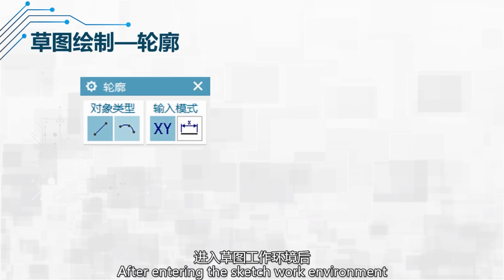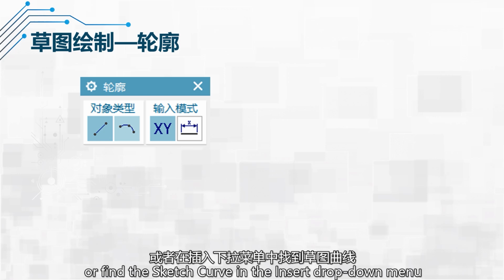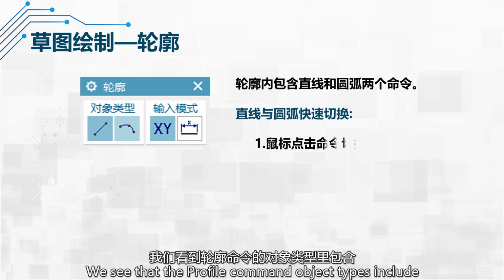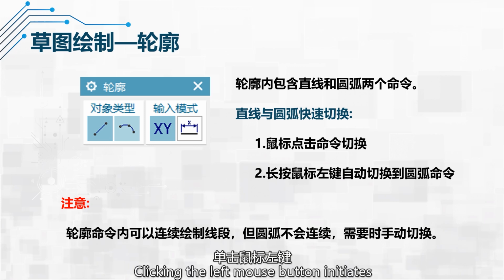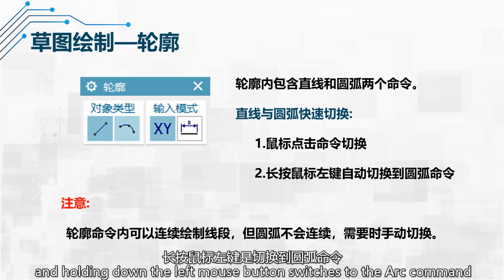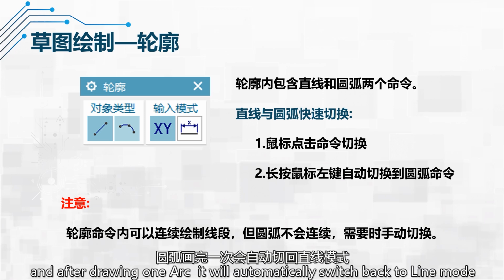After entering the sketchwork environment, click the Profile button in the toolbar, or find the sketch curve in the Insert drop-down menu and click the Profile command. We see that the Profile command object tabs include two commands, Line and Arc. Clicking the left mouse button initiates the line drawing mode using 2 points, and holding down the left mouse button switches to the Arc command. The line mode is continuous by default, and after drawing one arc, it will automatically switch back to the line mode.